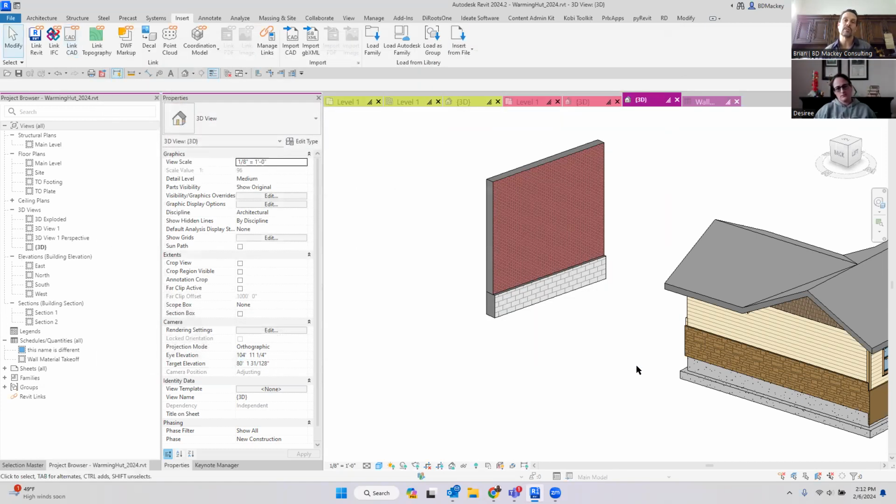Yeah, that was the only other suggestion, because it sounds, Ben, like you're just trying to bring this in. I'm pretty sure, don't quote me on this, but I'm pretty sure an STP file can be hosted on the Autodesk Construction Cloud, and Navisworks can view it. In Revit 24, any file that can be viewed on the Autodesk Construction Cloud can be inserted as a coordination model. So you can say, I want to bring in a coordination model from Autodesk Docs.